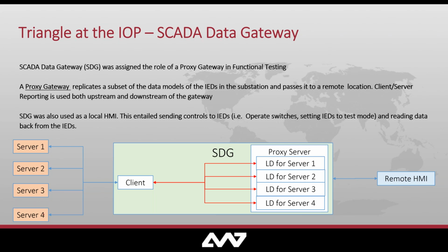So you're preserving the semantic data model of the devices here on the far left side. And I guess, at least in my eyes, one of the differences, especially in a world where you're converting between protocols, is that everything's not just a generic point. So let's say I was going from 61850 on the left over to DNP or 104 on the right. I'm losing the semantics.